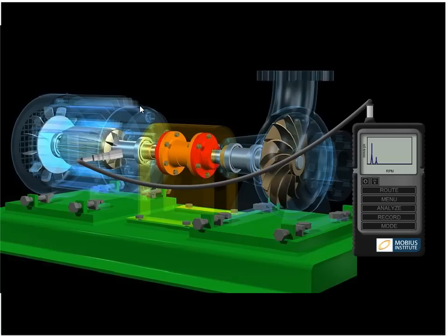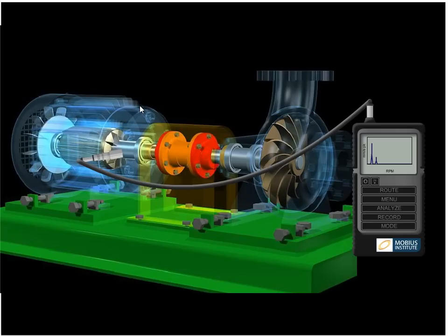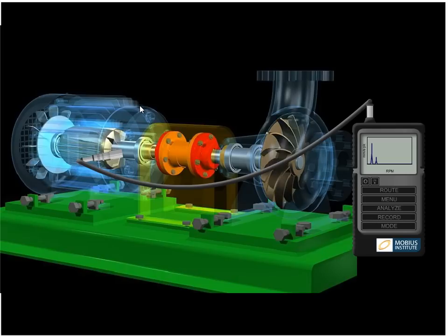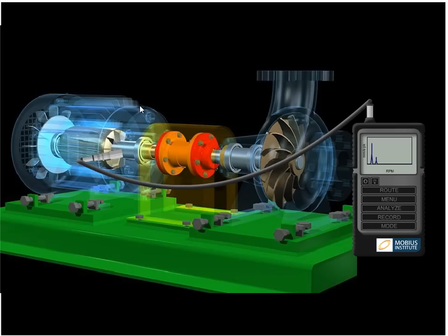And whether it's vertical or horizontal, those two positions tell us about radial vibration radiating out. So if there was misalignment and offset or parallel misalignment, or unbalance, we get a lot of that sort of up and down and side to side motion. But with angular misalignment, for example, and certain types of bearing faults, it's more sensitive in the axial direction.